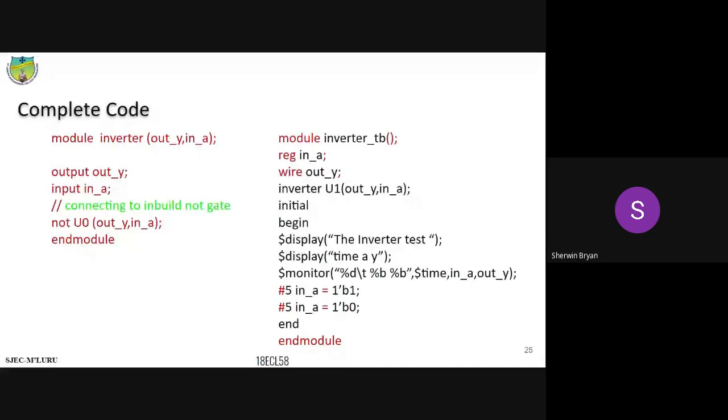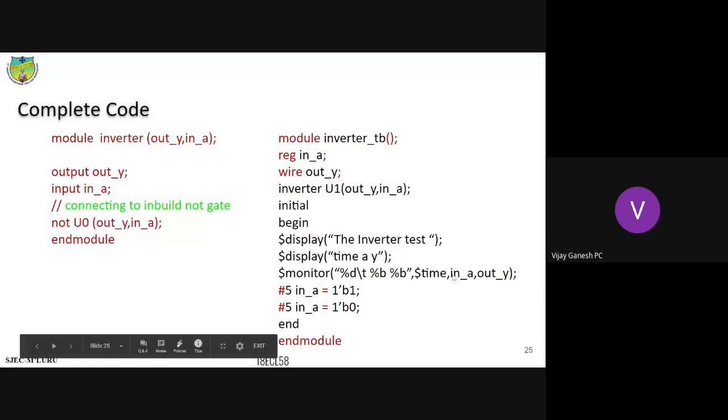In the module monitor, it displays the values whenever there is a change, right? Yes. So here time keeps on changing. Why doesn't it display 0, 1, 2, 3? See, when I say time, it will call for the input and output. Here in the monitor, we have given a underscore in comma out underscore. These are the things which it has to monitor. When I use a dollar symbol, it will neglect that. It is a predefined variable, which the monitor will ignore. Whenever I use a dollar symbol, it tries to ignore that and it takes only the required ones.